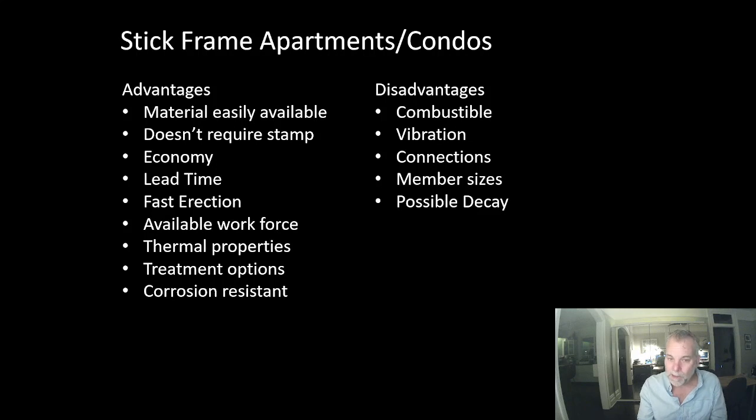Moisture is a challenge. Not that moisture is a problem. We keep it inside the building envelope, it stays dry, and that's not a problem. But if it does get wet, then the structure can be damaged. So if there's a fire, even if the structure doesn't burn, if the building gets saturated by firefighters, that can lead to having to demolish and reconstruct the building.